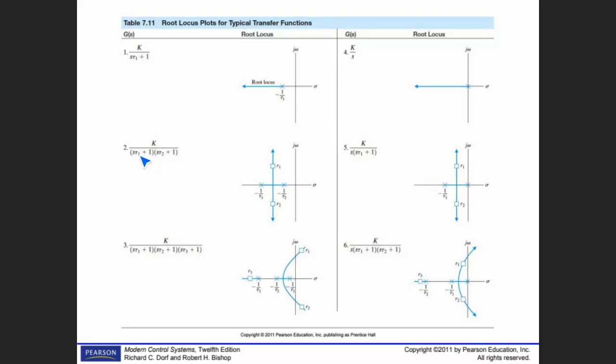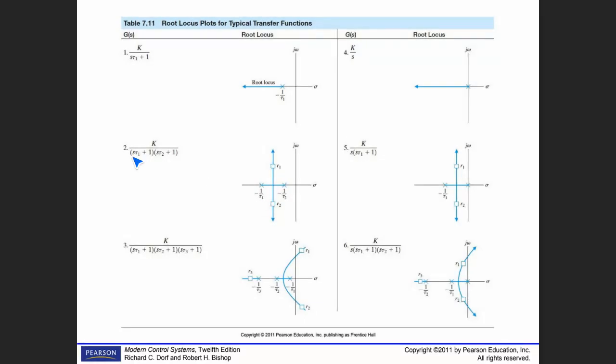So one of the poles was -1, the other one is -2, which represent, if you write like this, the time constants of this first equation, T1, T2. And of course, the trajectory is again parallel to the j omega axis. It's a second order system, parallel to j omega, and always stable. Is nice.